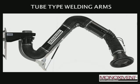One thing to think about is the environment and what we're doing. If we're in a really dirty, dingy, greasy environment, we may want to use an internally supported arm to protect that structure. On the other hand, if the exhaust is corrosive or just nasty, then we would probably want to use an externally supported arm. And we also get better air efficiencies with the externally supported arm because there's no obstruction to the internal hose environment.